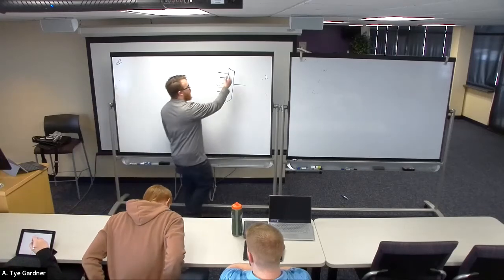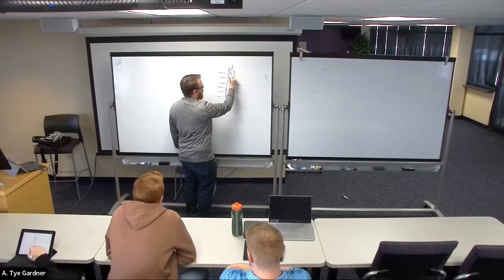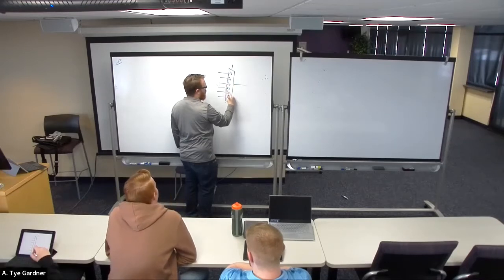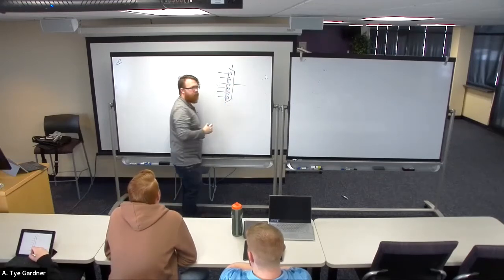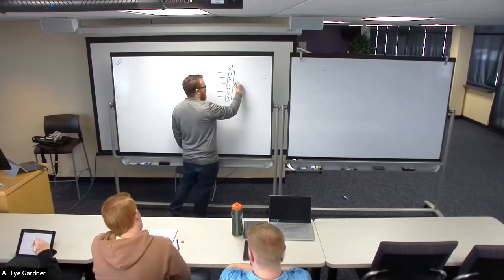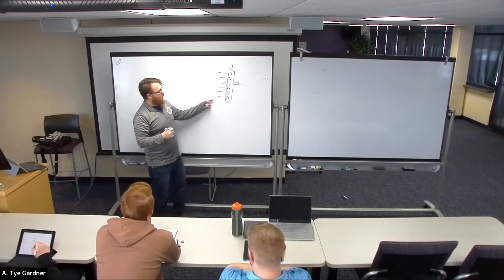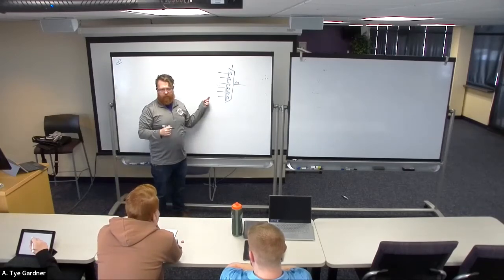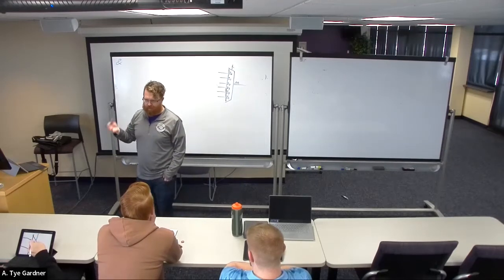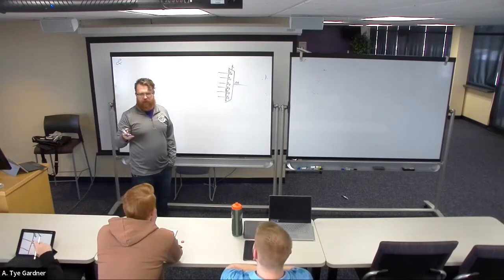Because if there are 6 choices, I0, I1, I2, 3, I4, I5, then what that's saying is my M output needs to choose one of 6, right? And it's going to look at this select signal, but that select signal can't be just 1 bit because it has to be able to choose 6 different options. And 6 is 3 bits, right?